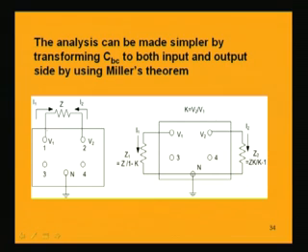Now, we want to simplify the circuit, and Miller's theorem says that this Z, which is between V1 and V2, can be distributed between 1 and ground, that is node N, as well as between 2 and ground, that is N. The ratio between the voltages V2 and V1 is say K. Then we can distribute Z into the input and output circuits, removing it completely from this part between 1 and 2, to make the circuit simpler.